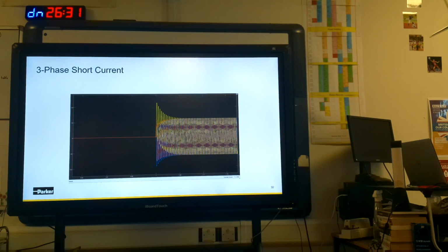So here's the warning. If you go around and you look at the rated current of the machine, the rated current of the inverter, you match them, and you go off and do your application, and let's say you were field weakening and it just happened to have a 200% short circuit current, and you go into one of these three-phase short circuits, which is a good thing, by the way, because we know that now, that could be really bad for your inverter.